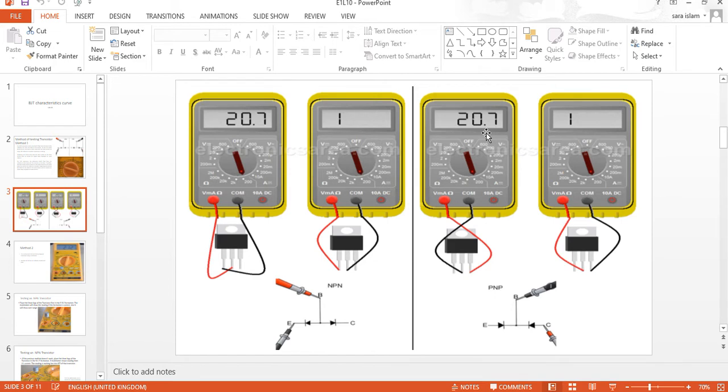And now you flip the connections and you connect your mid with positive, okay, and the other two, collector and emitter, with your negative. In this scenario, if you observe an open loop, it means your transistor is working fine, okay? On one side it's showing a value, and on the other side, if you flip the connections, it's showing open loop or one, for your specific multimeter within your lab, right? So it means that it's a normal transistor.